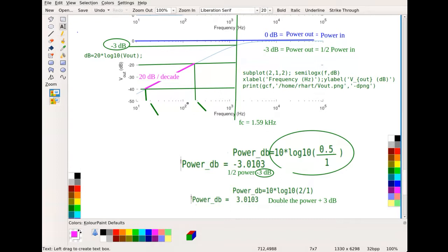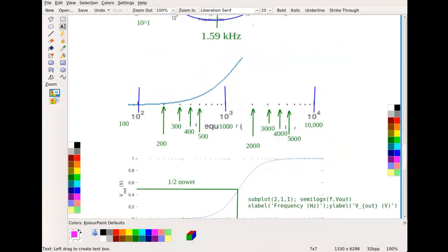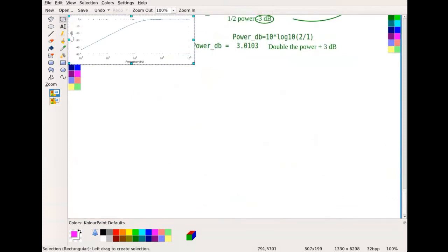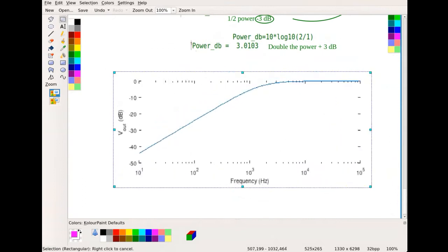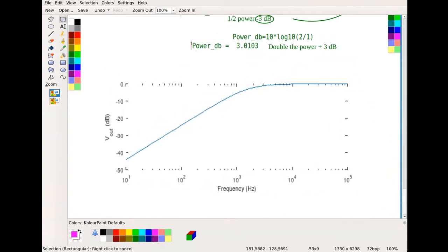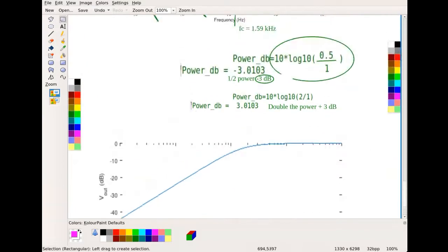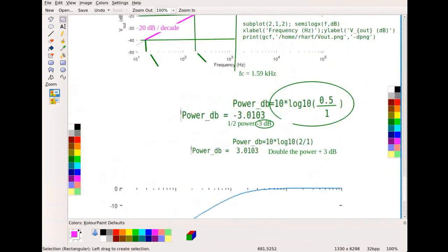because when you look at this plot, and I'm going to paste a new copy of it in here because I've already drawn on it so much. Okay, but you can sketch out a Bode plot in about 3 seconds flat for an RC circuit, because all you got to do is calculate that cutoff frequency, right?